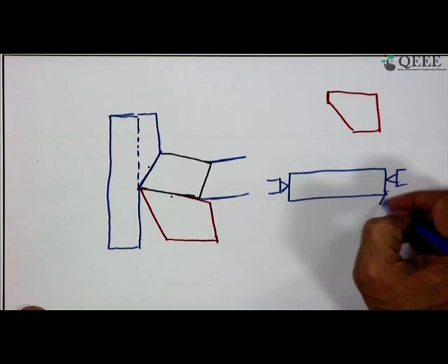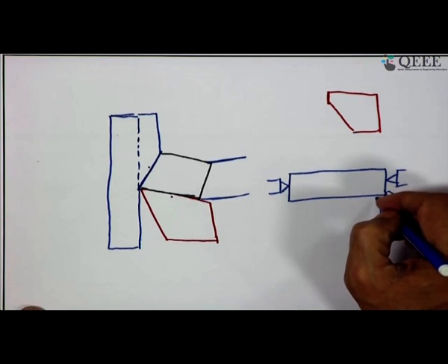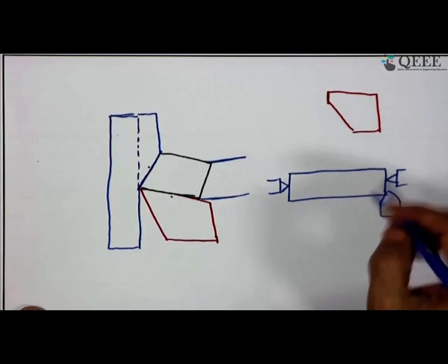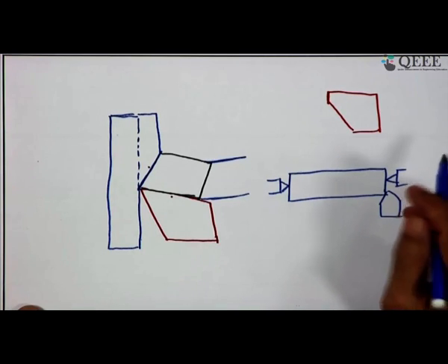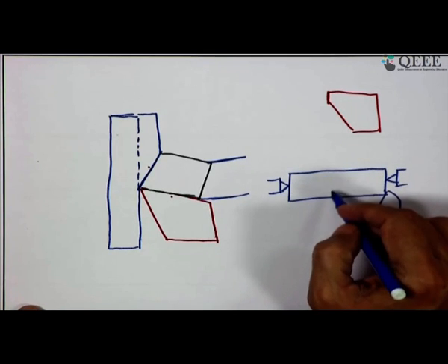So, when we have such kind of material, and we machine it at a very high speed or temperature by some reason very high, then to certain depth, you have a temperature profile. That is called the temperature gradient. Whatever may be, the cooling on the surface will be faster. So, this will try to contract the layer beneath it.